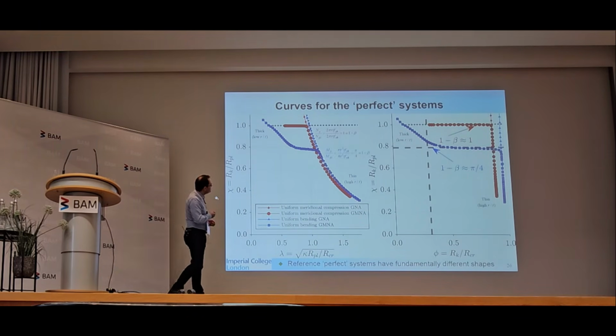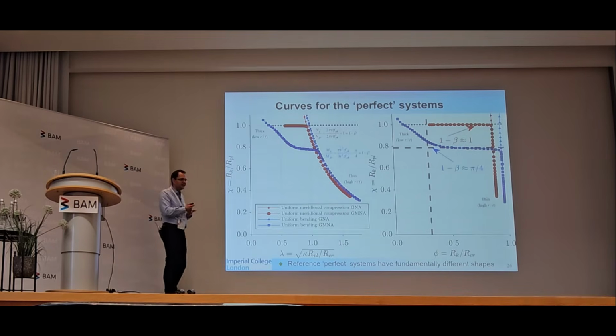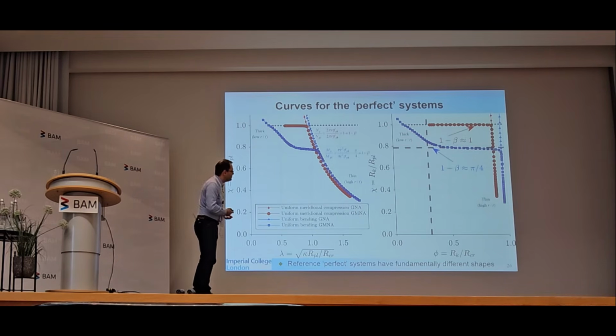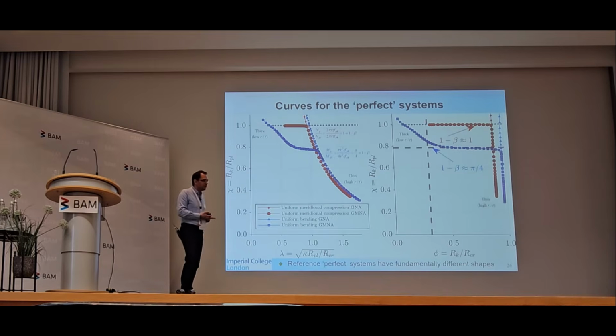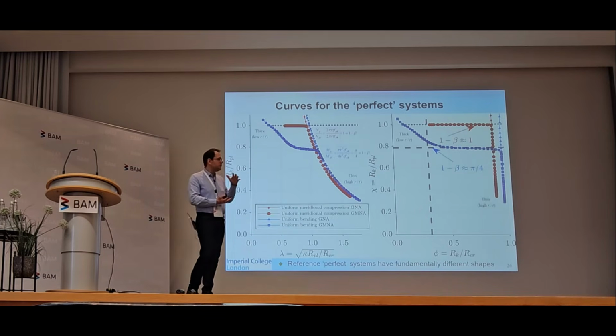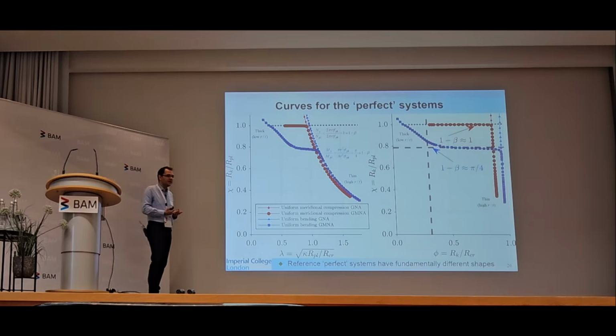So these are capacity curves for the perfect shell, a perfect cylinder of a non-ovalizing length. So none of the nonlinearity that you see here is due to ovalization. The red curve is axial compression, and the blue curve is bending. So the question now is, at what point does a cylinder under axial compression get affected by yielding? This can be answered by considering it just as a beam, because the point of first yield is the point of full yield, because the stress state is uniform.